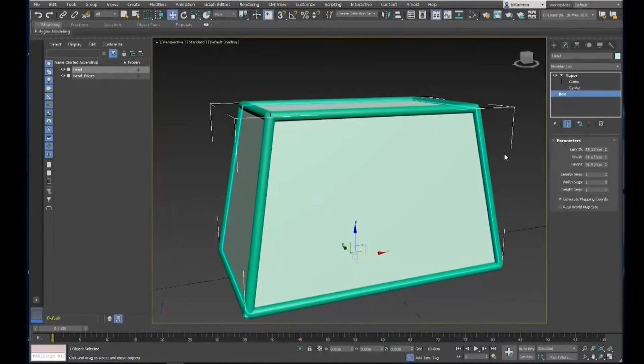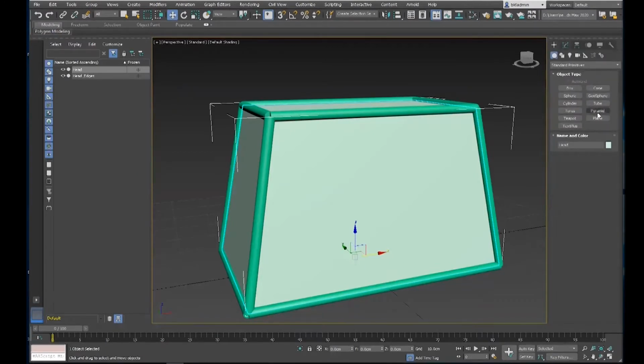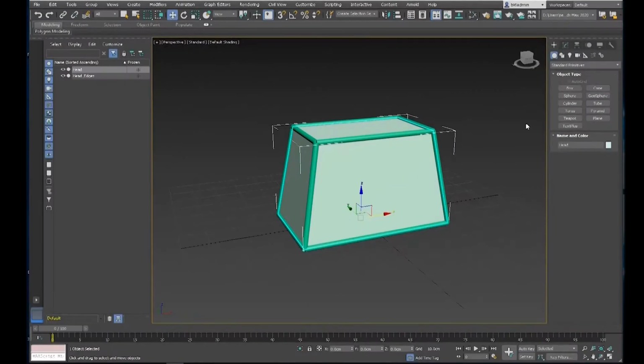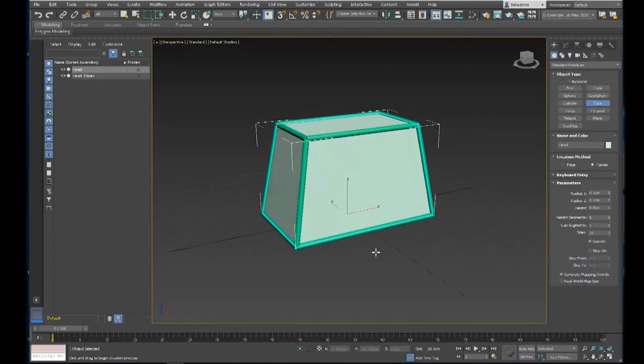So tube is a standard primitive, so we can go here and create a tube, but hold on for a second. Before you actually create this, let me show you the options and explain them. One typical option: we are creating a tube, and in the perspective view the active grid is the floor grid. So whenever you create something, it will be placed on the floor. The tube works this way: you have one radius, then another radius, then the elevation, and then clicking again, and you're done.